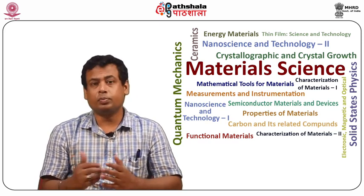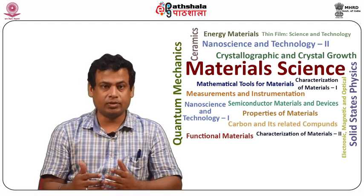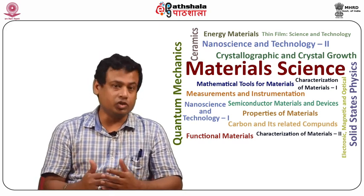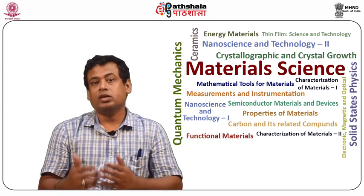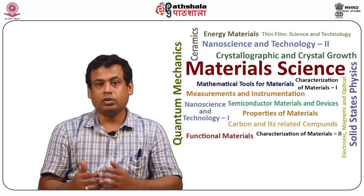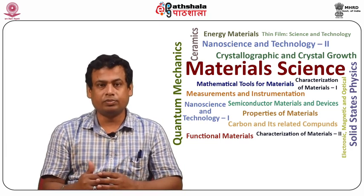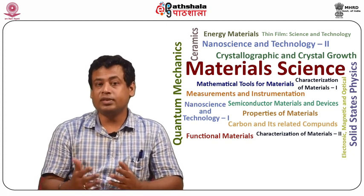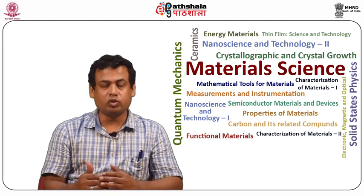During semiconductor processing, fabrication of micro or nanostructures rearranges the additives by deposition, subtractives by etching and surface dopants by annealing. Etching out the unwanted materials and depositing the desired materials for a complete nanostructure or device structure is the key concept of microfabrication processing.